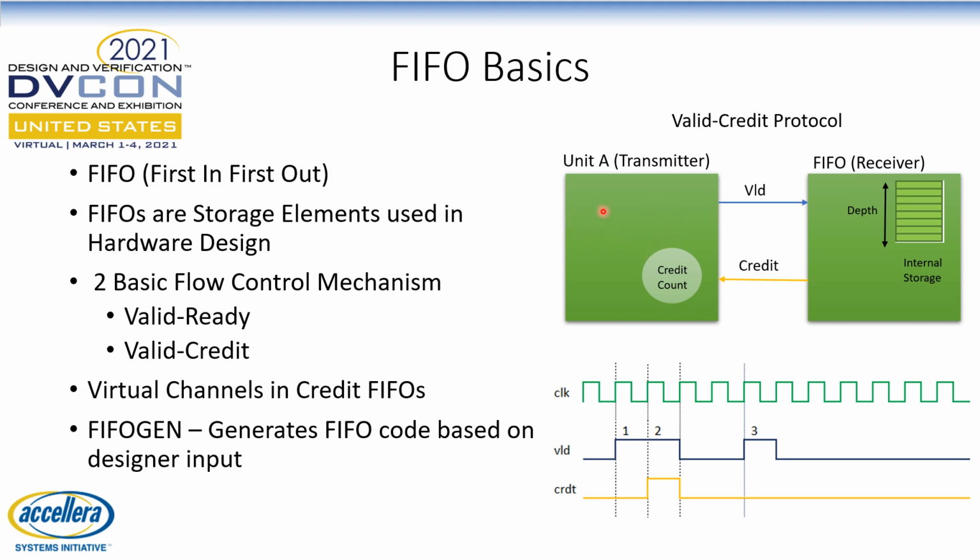And when the source tries to transmit a packet, it first figures out which credit class it belongs to and then decrements the appropriate credit counter. And the credit return also comes with the information of which credit class this credit return happens for, so that the appropriate credit count can be incremented.